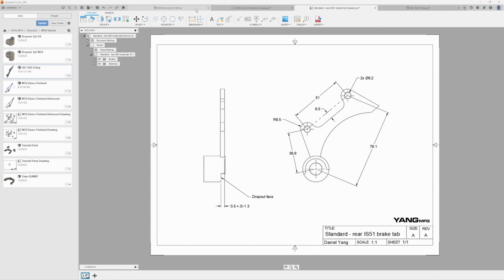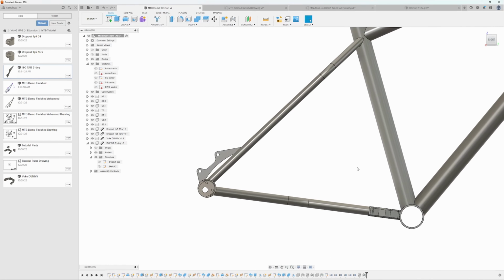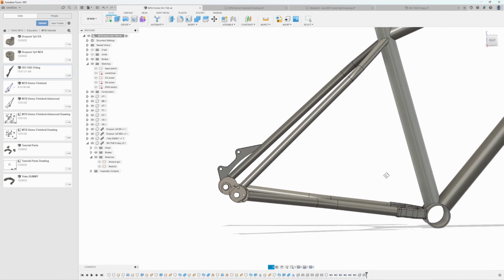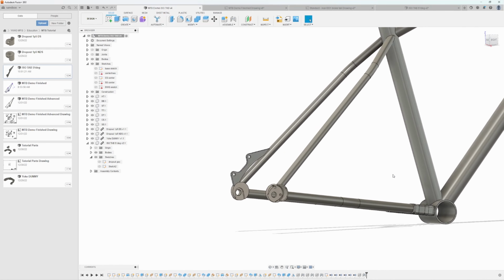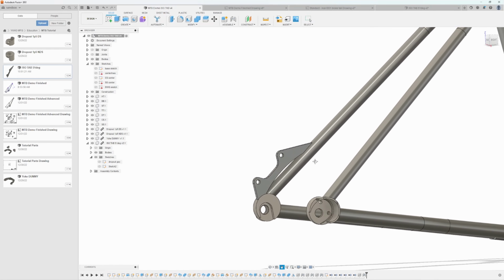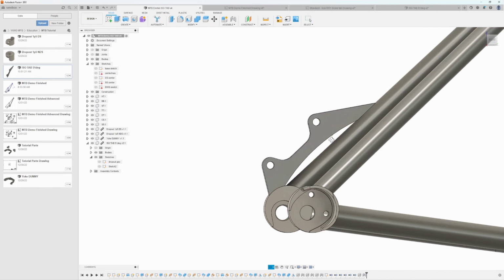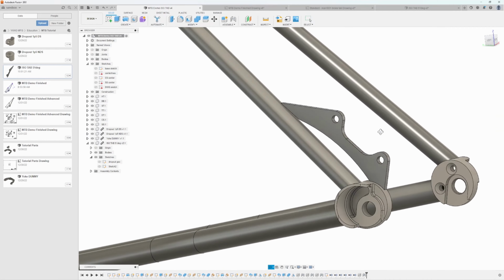Drawing your tab is good for a few reasons. You can customize the aesthetics of your bike, it's cheaper, laser cut tabs are roughly $4 to $5, and it'll save you time. Because these tabs are designed to your seat stay angles and diameters, they don't require as much filing, bending, and eyeballing to get it to fit.